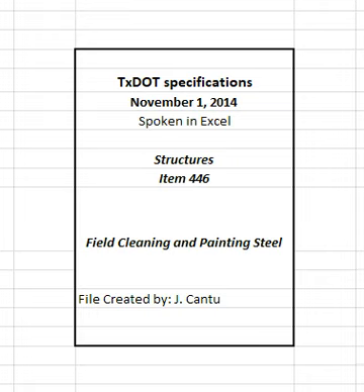4.9 Storage and disposal. Collect all waste generated by cleaning and painting operations as necessary to prevent release into the environment. At a minimum, collect all waste before leaving the job site each day. Handle and store the waste as if it was hazardous or universal waste until classification is made. Follow the requirements of 30 TAC 335 for on-site handling of the waste.